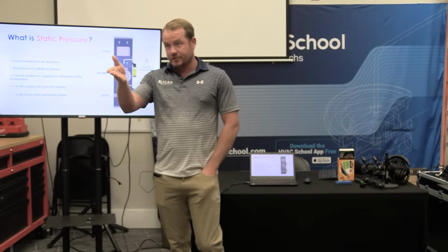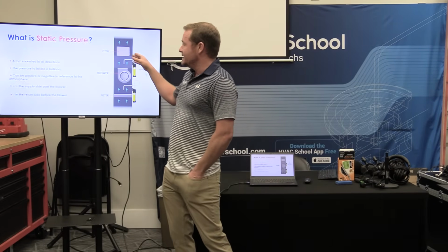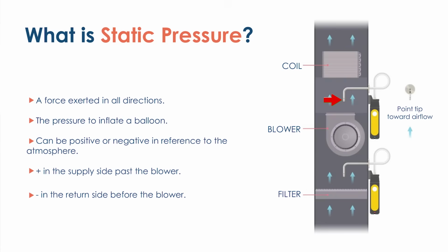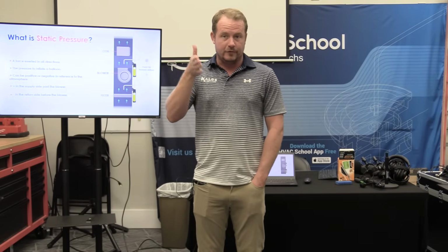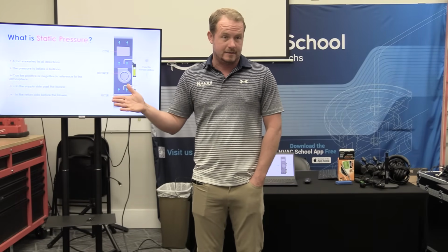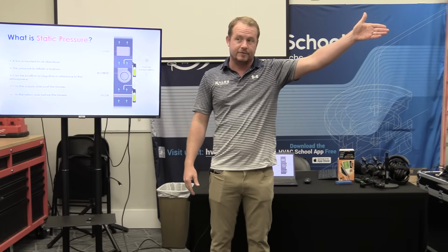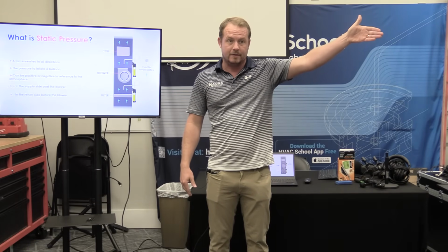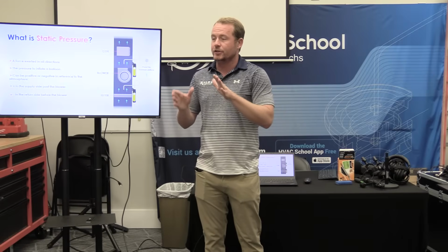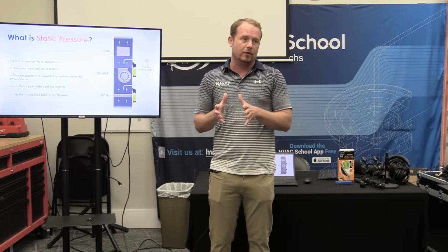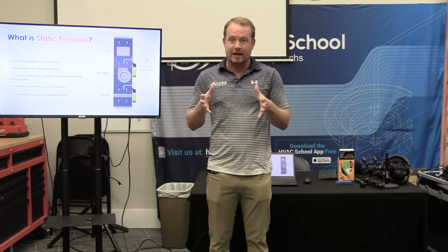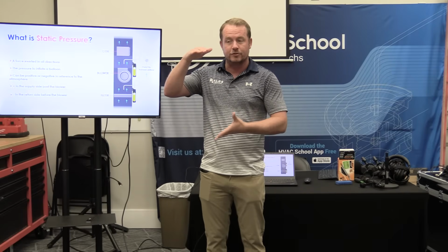You will have a pressure drop, that is true, but the particular reason why we measure it this way on a gas furnace is because in a gas furnace, the evaporator coil is actually a different piece. So when you install a gas furnace, you have the furnace and then you have the coil, and they come in two separate boxes. They don't come with each other, right? On a fan coil, an air handler like this one here in the classroom, the coil comes in the box, right? So when the coil comes in the box, that means the unit is rated with that coil already in place. Meaning the manufacturer knew the coil was in place, they already know the pressure drop across it.